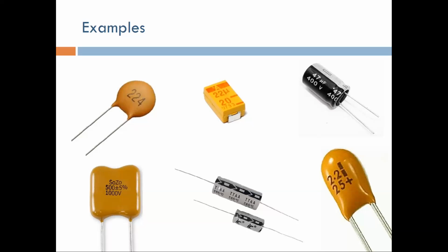When something like that explodes on a printed circuit board, it can ruin the printed circuit board itself. Because as I told you before, usually printed circuit boards are multi-layer. If this explosion destroys some of the tracks in the inner layers, then there is no way you can repair the printed circuit board. So you should really be very careful. If you are repairing a particular printed circuit board and you're replacing a capacitor, and you put it in the opposite direction, this will be a big problem. Just be very careful about that.